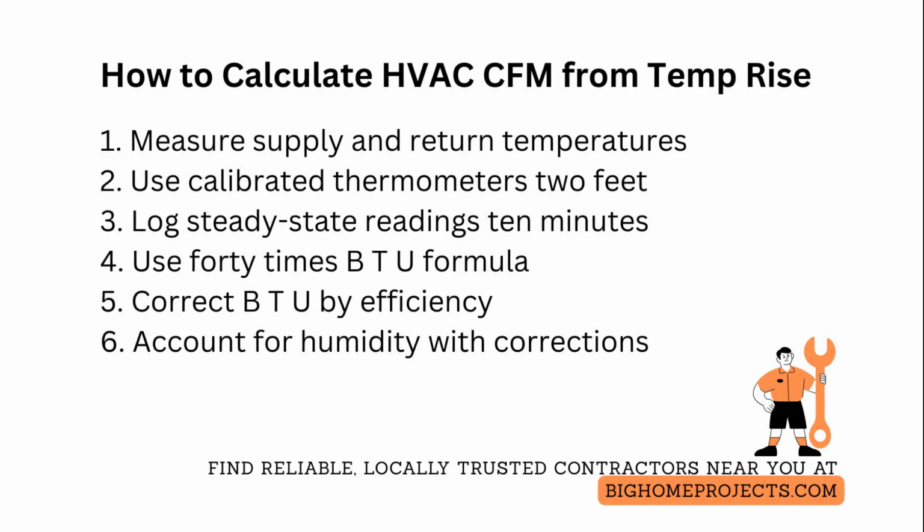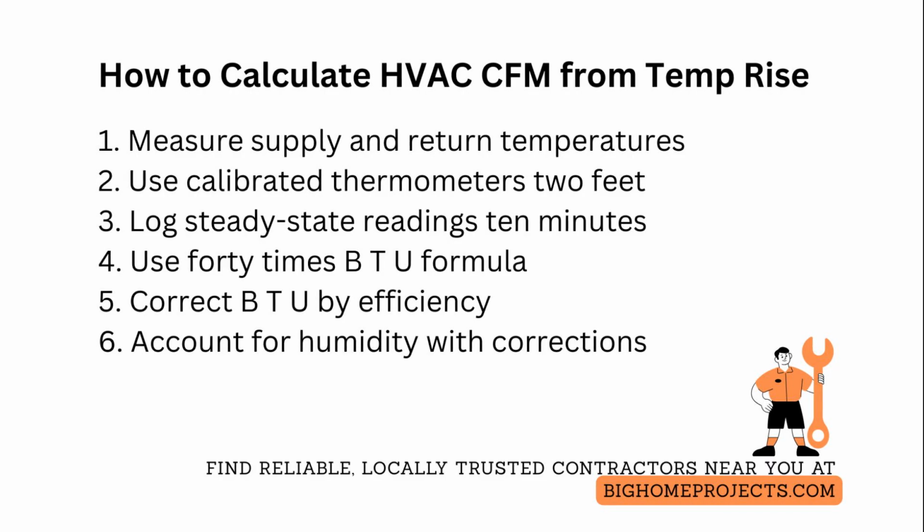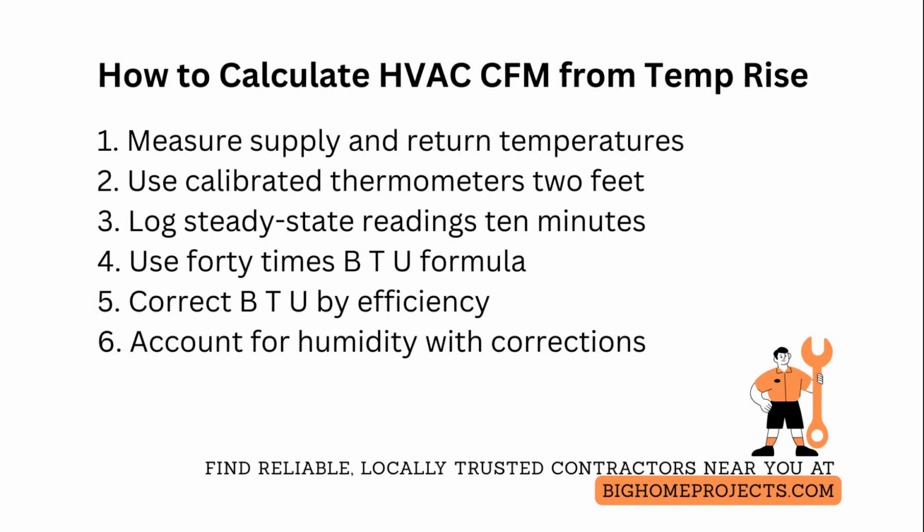Finally, when using probe holes for return or supply temperature, plan probe insertion locations in non-critical sealing points and mark them so they can be sealed immediately after testing. Leaving holes open introduces bypass air that skews future seasonal performance and can lead to unstable control and higher energy